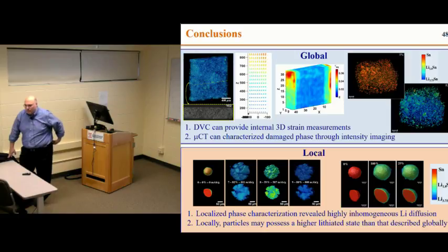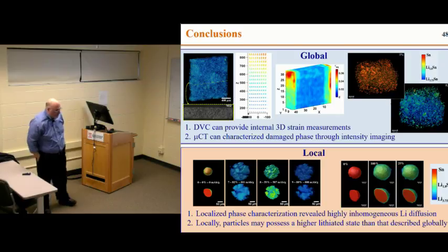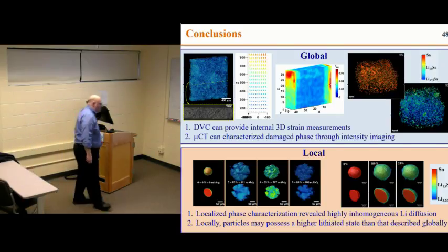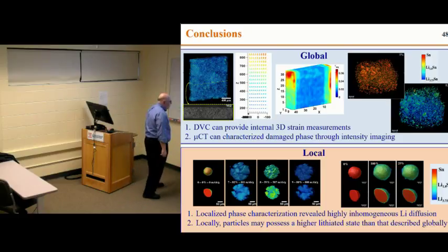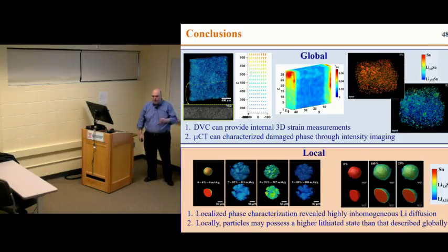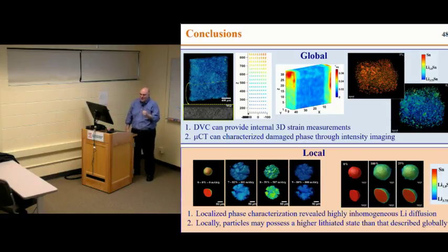Go ahead. So I guess my main question is, how far in the future do you see this applied to asphalt concrete, which has a sample size that we usually see higher than this? It's very viscoelastic, so probably keeping the load constant would be a higher challenge. Well, okay. Let me start with the second first, right? I don't think it's more viscoelastic than this. But even if it is, that is not the biggest challenge. I think that is something we could fix by some kind of feedback, right? You can do some measurements and then feed them back. You just need a more sophisticated loading machine than the very simple machine we had here.